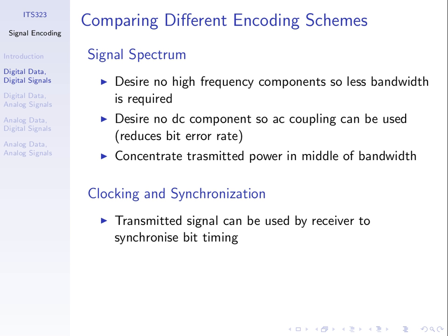Let's say in the middle of the interval, the receiver records the value and converts it to a bit. So at time 0.4, what is the value? It's low. If we use non-return to zero, that corresponds to a bit 1. These are the transmitter bits: 1, 0, 1, 1, low, high, low, low.